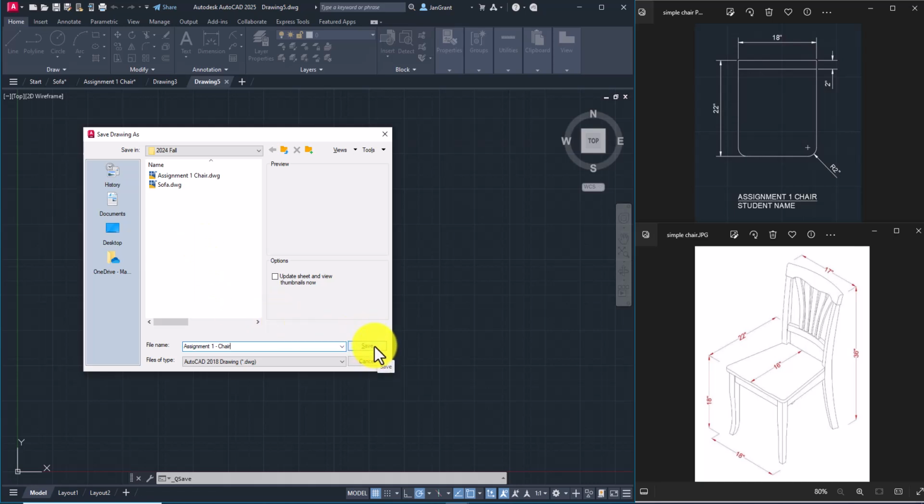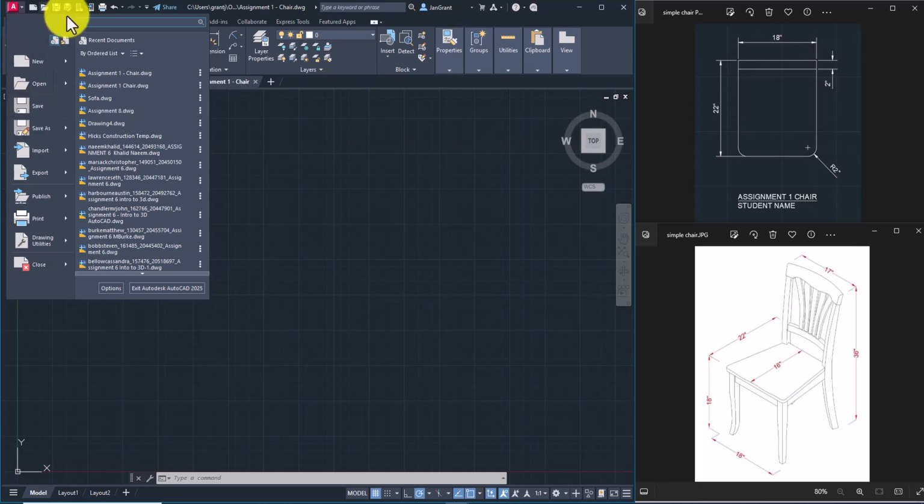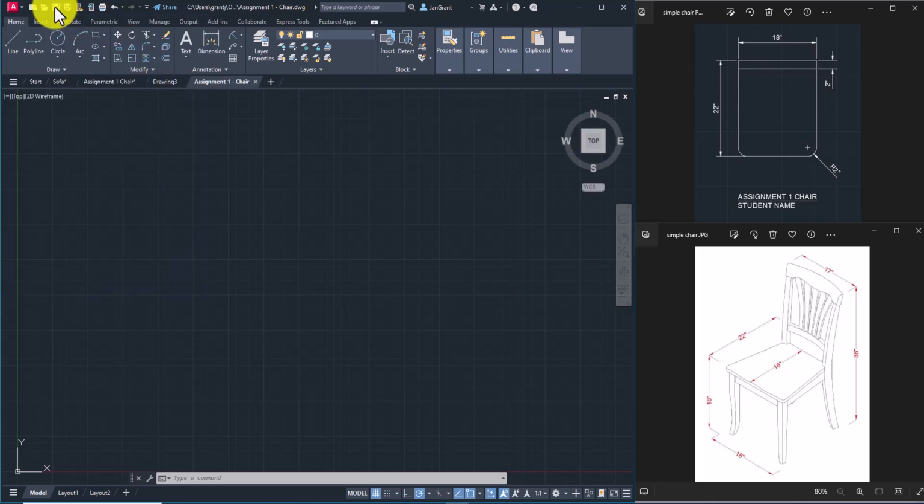There's a lot more that we're going to be covering, but this is just to get us started here. Now that it's saved, it is a DWG extension. And just so you know, the first time that I manually come back up here and pick Save, either here or you see all of these match the icons up here, I can click on Save. The first time that you pick Save, it doesn't show you, but you're creating now a backup file in that same folder with the BAK. Please don't submit the BAK when you submit this project in Canvas. We want you to send the DWG.